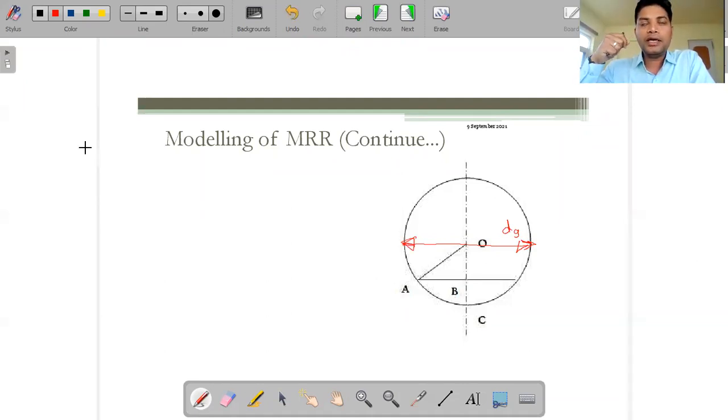The material removal rate will be different for the ductile material and for the brittle. The reason, as we discussed yesterday, is that for the brittle material the removed material becomes semi-spherical in nature. It is exactly not that much in size as the figure shows, but very small, because the size of the abrasive particles we are using is in the range of 10 to 50 microns. When it impinges over the workpiece surface it removes a very small quantity of material, but we are just assuming that it is in a semi-sphere form.